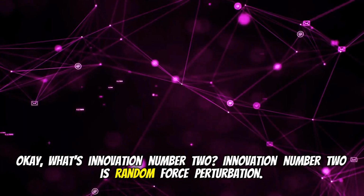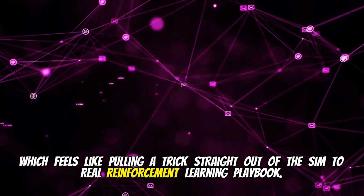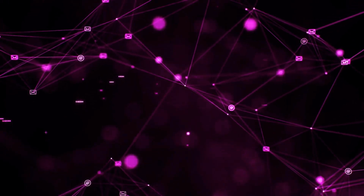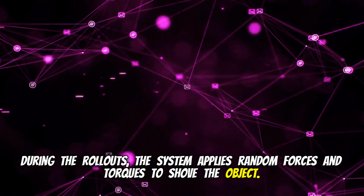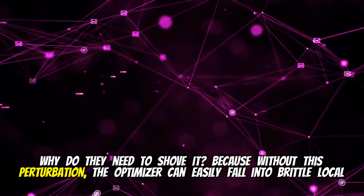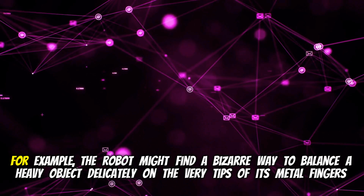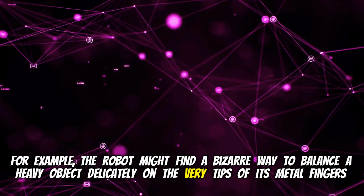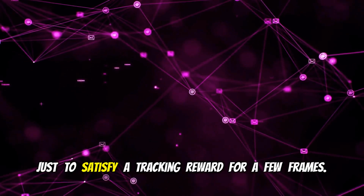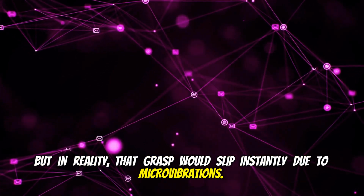Innovation number 2 is random force perturbation. Which feels like pulling a trick straight out of the sim-to-real reinforcement learning playbook. It really does. During the rollouts, the system applies random forces and torques to shove the object. Why do they need to shove it? Because without this perturbation, the optimizer can easily fall into brittle local minima. For example, the robot might find a bizarre way to balance a heavy object delicately on the very tips of its metal fingers just to satisfy a tracking reward for a few frames. And in simulation, it looks fine. But in reality, that grasp would slip instantly due to microvibrations.